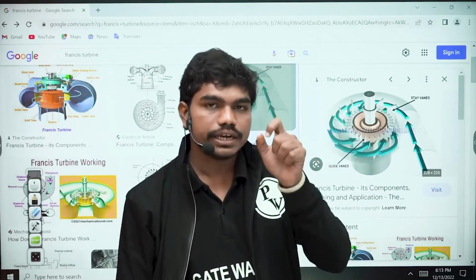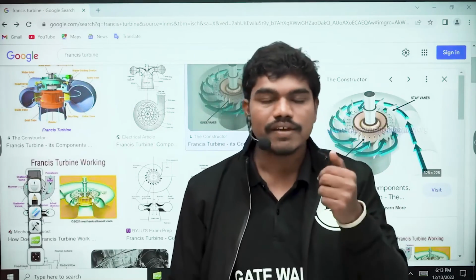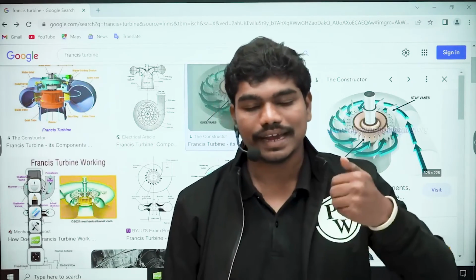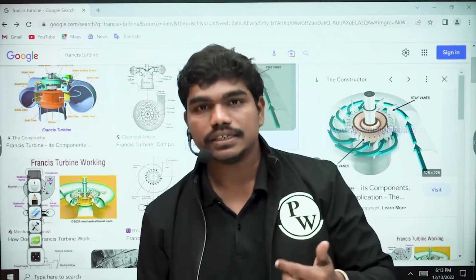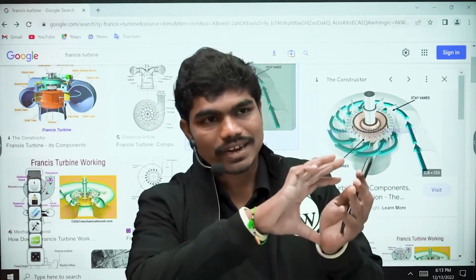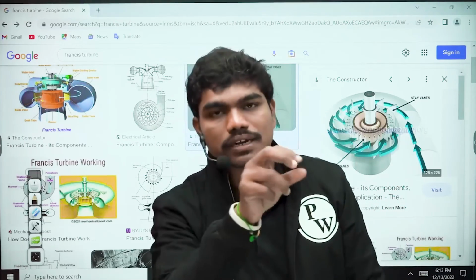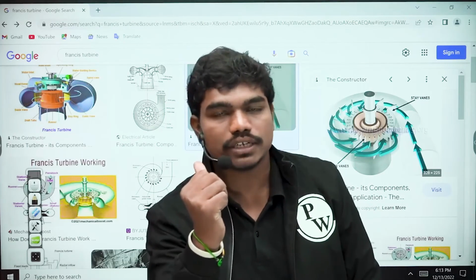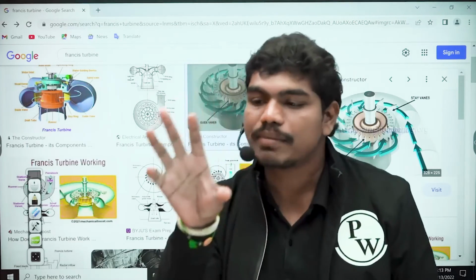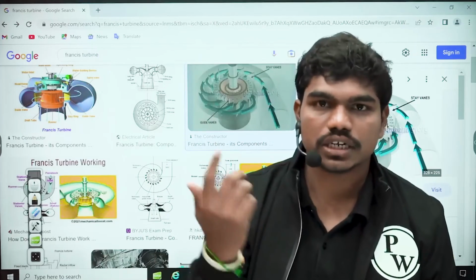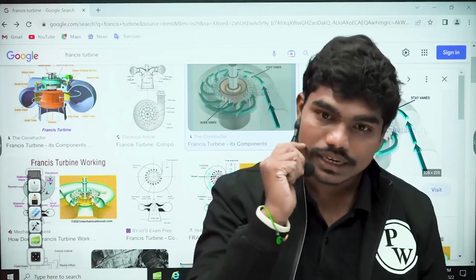Okay, because here your main job is to make this VW2 value 0, so that the head supplied to the turbine actually increases. So from a design point of view, they will bend the flow passages radially, so that at the exit there is no tangential velocity for the fluid. Whatever fluid is coming out is no more used for the rotation.